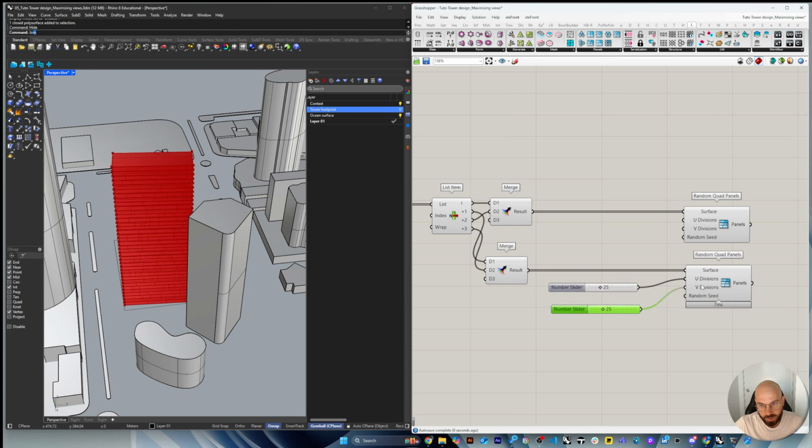And then here, if I have the same number of floors, I could actually grab my number of floors. So every time I change my number of floors, it will update. So I got 38 floors. So I could actually grab that slider, plug it here, and now every time I change, I always have a floor to floor. Yeah, I think I need +1.